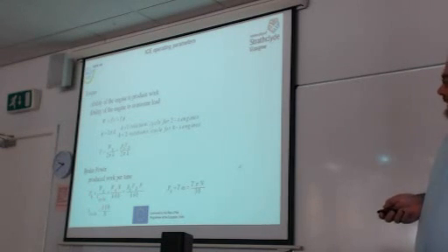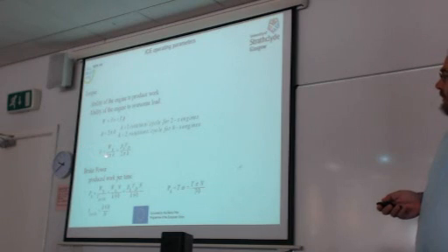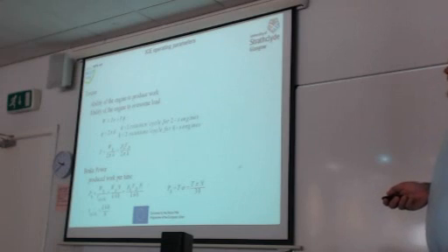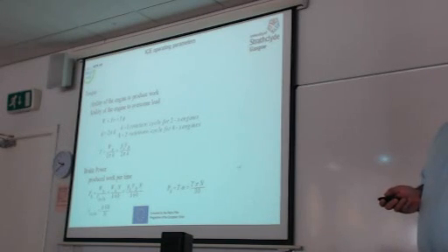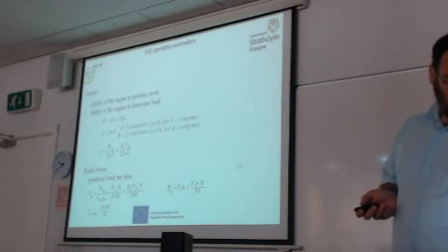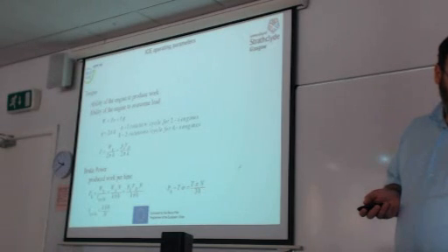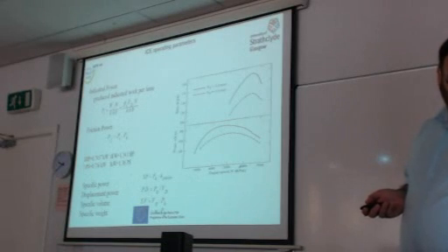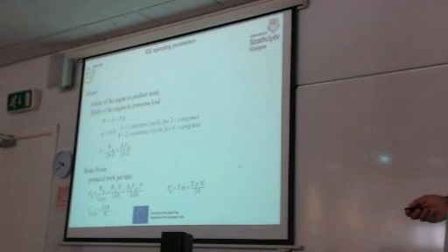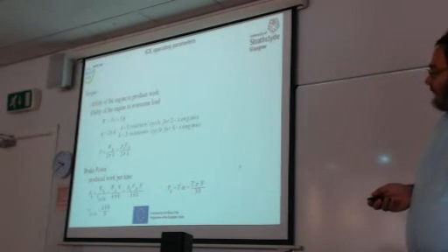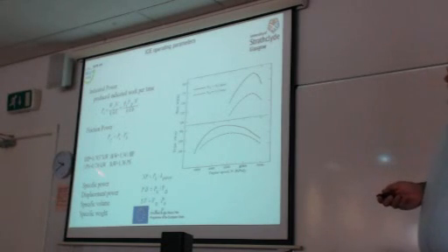Then other important operating parameters are the brake power of the engine, usually in kilowatts or in horsepower, which is the brake work delivered in one cycle over the duration of the cycle. So this is the definition of brake power. And of course the torque, which characterizes the ability of the engine to produce work or to overcome a load. Torque is the brake work over the duration of the cycle, 720 degrees for four-stroke engines, 360 degrees for two-stroke engines. And of course, the very useful relation that connects brake power with torque: brake power is torque times angular speed.